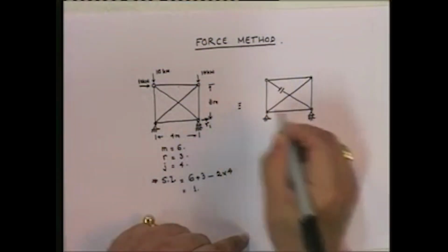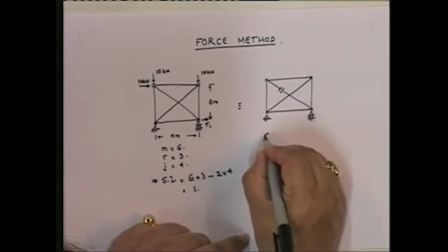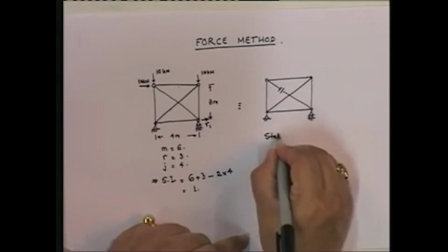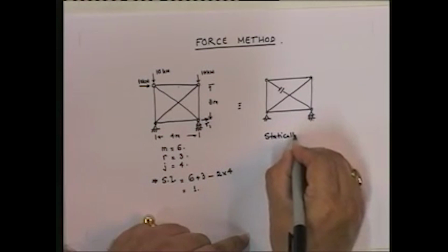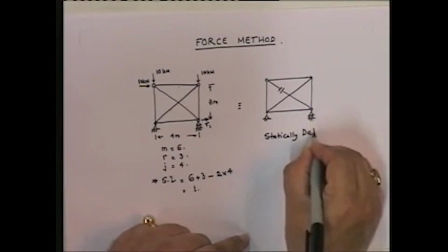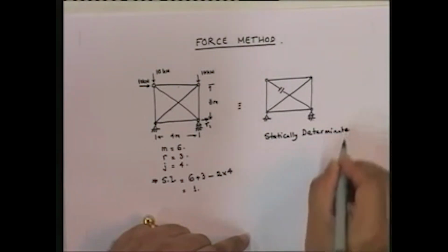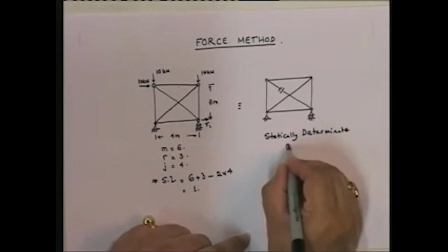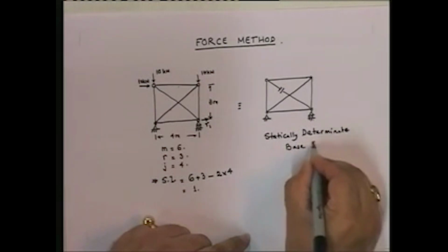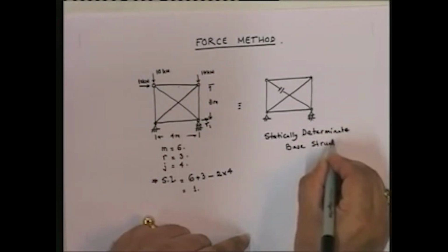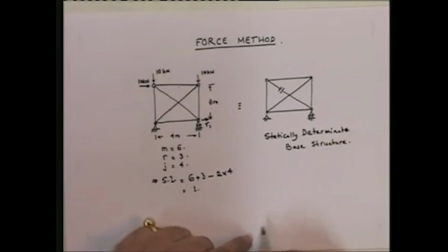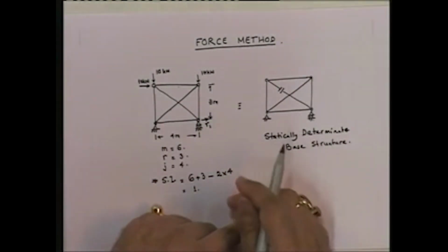The first thing that you do in the force method is you find out the statically determinate base structure. So you find out the statically determinate base structure.